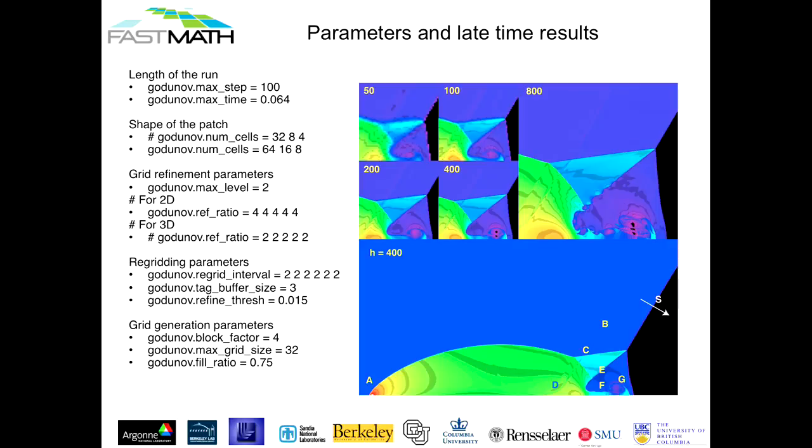The whole problem is inclined. S is the shock coming in at Mach 10. This is somewhere near the end of your simulation. It'll start on the far left, first hitting that edge, and then as it comes over, there's post-shocked subsonic flow behind the Mach stem. This side is still unshocked fluid. In these regions, you have various effects that are labeled. There is a roll-up. There's a Mach line. E and C are Mach lines, if you know what those mean.